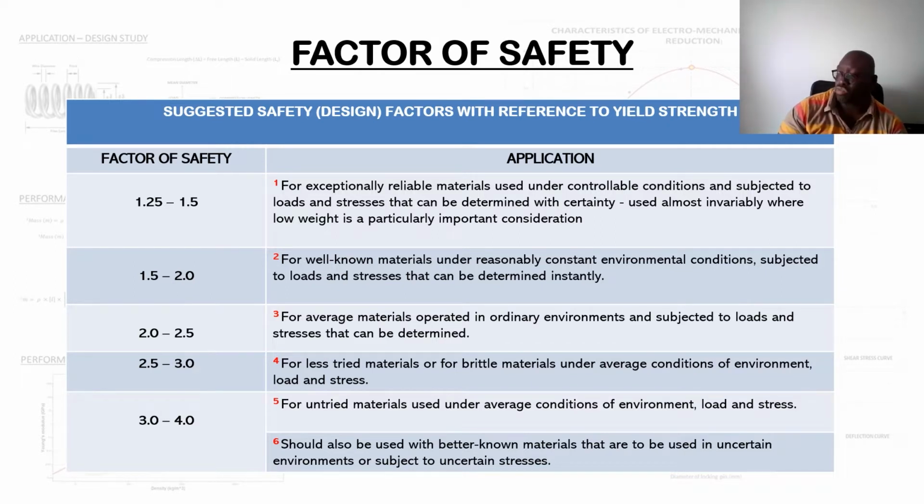Or if the material is quite brittle and there's very little plastic yield after the yield limit, then you probably need to think about whether it is smarter to have a larger safety factor. Again, there may be too much uncertainty about the probability of quick changes in the material or in the operational environment of the component, which the designer doesn't have a lot of control over.